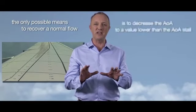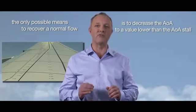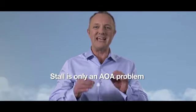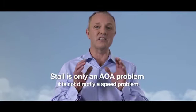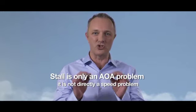When the flow over the wing is stalled, the only possible means to recover a normal flow is to decrease the angle of attack to a value lower than the angle of attack stall. Stall is only an angle of attack problem. It is not directly a speed problem. Remember these last 2 points.